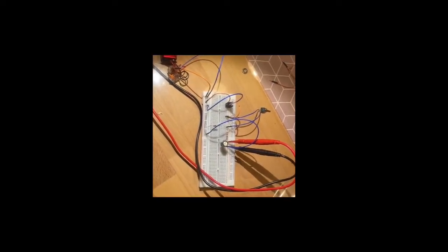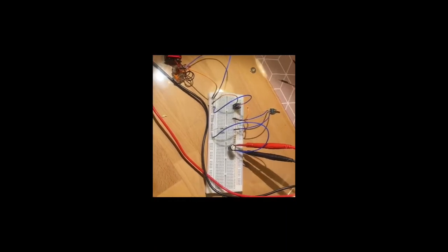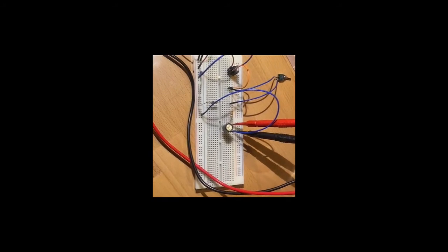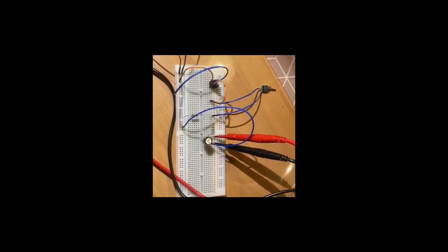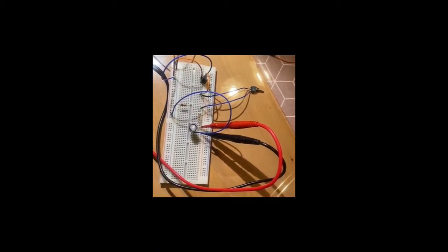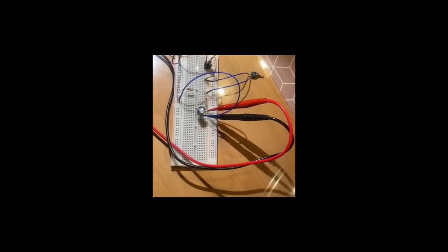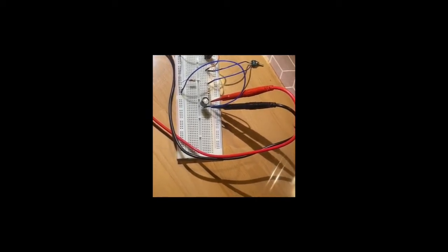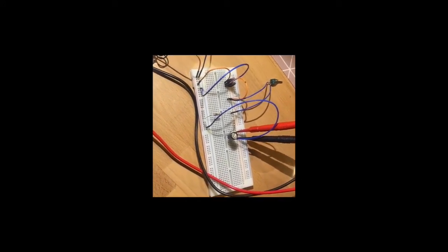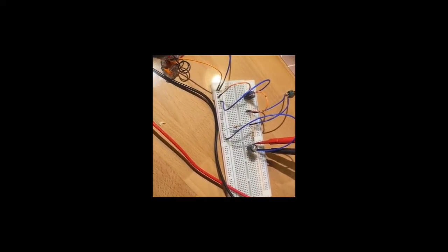So now let's have a look at the experiment. On the top, on the left, we can see the supply with the plus and the minus terminal, and from there we get to the voltage regulator, where the voltage is regulated at 5 volts, and the connection to the two resistors, the 10 kilo ohm resistor with connection to the ground, and the 47 kilo ohm resistor with connection to the capacitor.